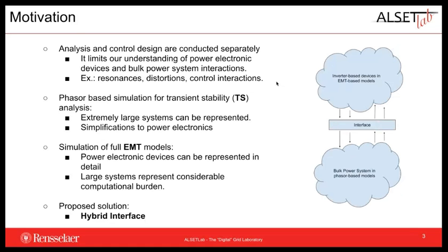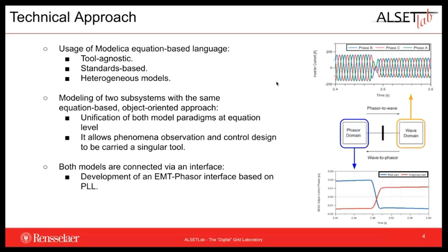And in order to overcome this issue, we proposed a hybrid interface. But I'm not talking about just a co-simulation hybrid interface. I'm talking about using Modelica to create a heterogeneous model that unifies both EMT and phasor-based models at the equation level using a filter and a phase-locked loop.